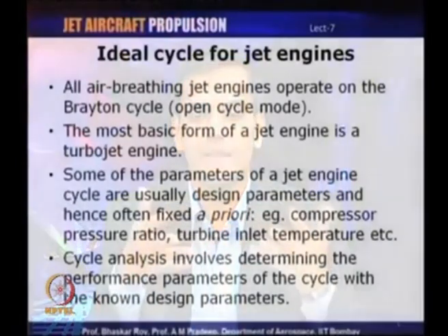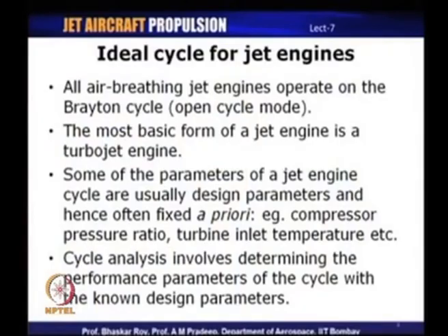Now, when we have to analyze a turbojet engine, we use something we have discussed in one of our earlier courses, that is known as cycle analysis, wherein we carry out a parametric analysis of the jet engine based on some of the design parameters that are known, like compressor pressure ratio, turbine inlet temperature, etc. And then we find out the performance of the cycle, like the thrust, the efficiencies, the fuel consumption, etc., based on some of these known parameters.